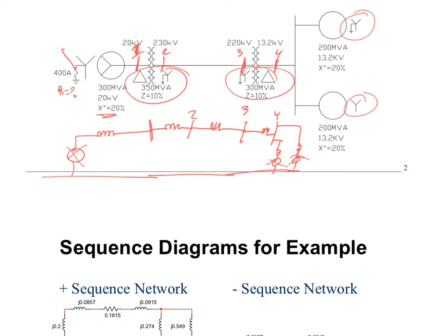When you go buy a neutral grounding resistor, you tell them what the voltage is and what current you want. Hint, hint, wink, wink. If you know the voltage and the current, can't you solve for the resistor size? So how do you solve for R? Pardon? V over I. What's the value of V that I put? That's in per unit. I need it to be in ohms.